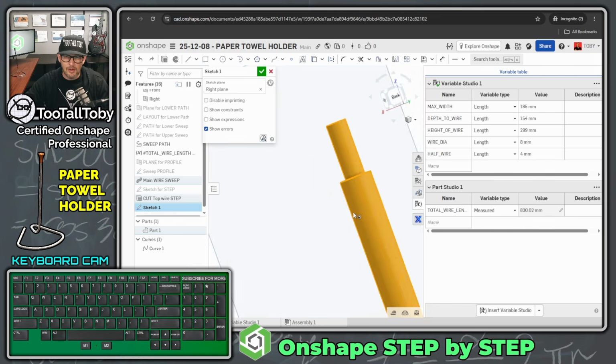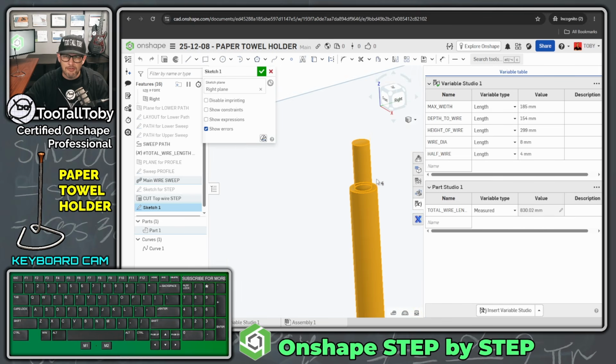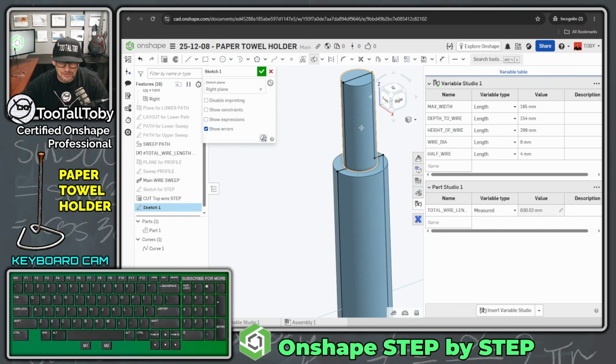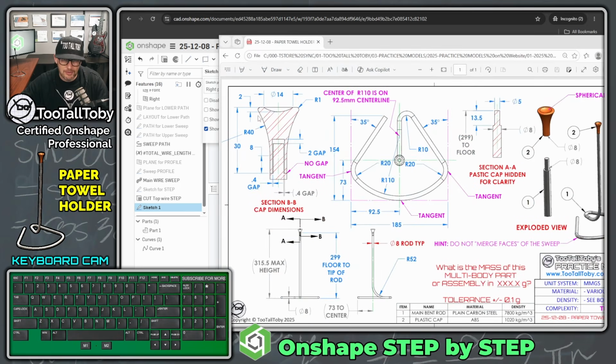And then I'm going to tell Onshape to decipher wherever the right plane is running through those faces. And I'm going to do that using this command here. It's underneath the use project command, and it's called intersection. So as soon as I click on that command, look at that. Onshape goes in and it adds in that sketch geometry. And that's so helpful because now I can reference that sketch geometry when I'm creating the geometry for this lid.